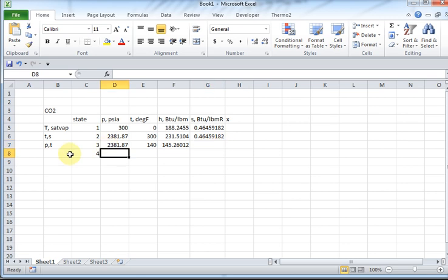The state 4 is the pressure and the enthalpy. True? Yes. The compressor is the best compressor we can have. It's adiabatic. Now, if the compressor has some cooling, then S will be lower. But I'm just assuming adiabatic reversible compression.